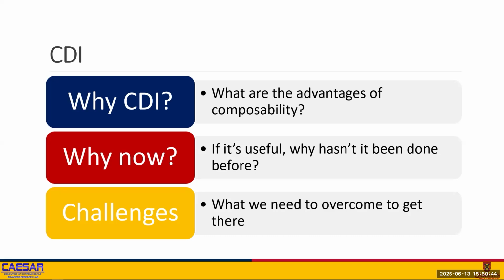If it's so useful, why hasn't it been done before? Creating these decoupled PCIe domains and managing all the translations of the addresses such that you can actually wire things into a server, expose enough devices such that you can expose a large amount of equipment, like an entire row of supercomputing equipment, and not flood your PCIe bus and run out of IDs or make your BIOS have to hack. You have to hack your BIOS. Like adding more than 64 PCIe devices to a typical server, you probably voided your warranty by hacking in a different version of BIOS so it'll scan it.